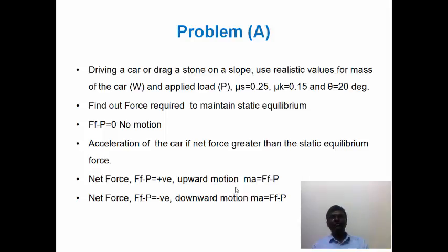Assume that the static friction is 0.25 and 0.15 is the kinetic friction, and the inclined angle is 20 degrees. So find out the force required to maintain the static equilibrium. If it is a car, how much brake force or how much friction force is needed to maintain the car in a static equilibrium on a slope.